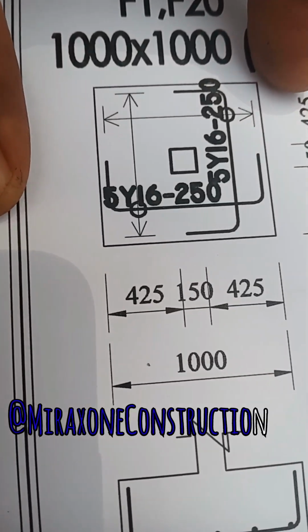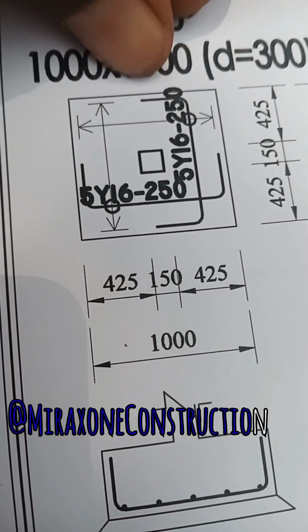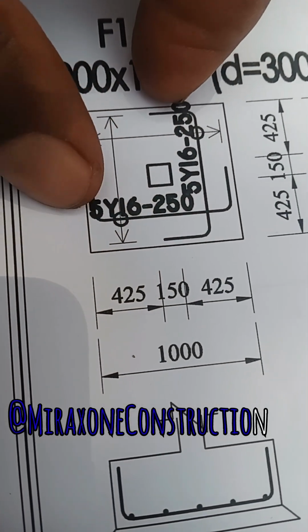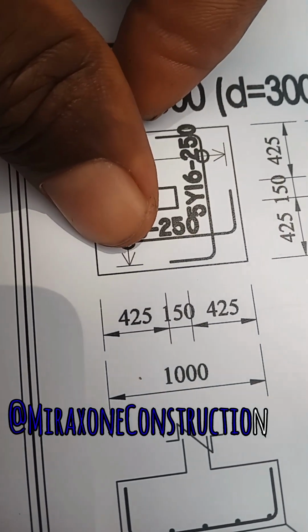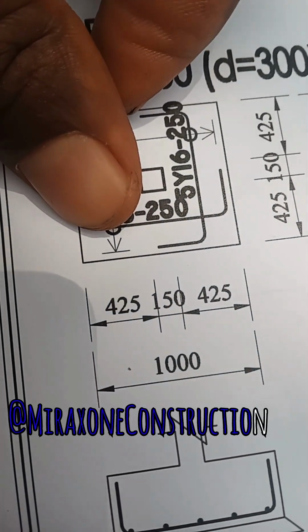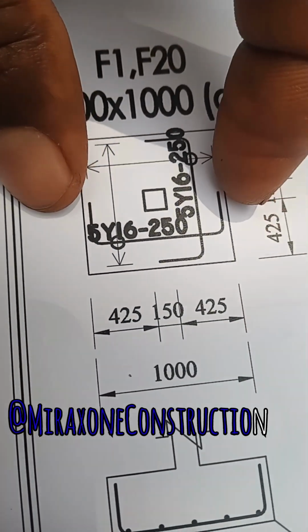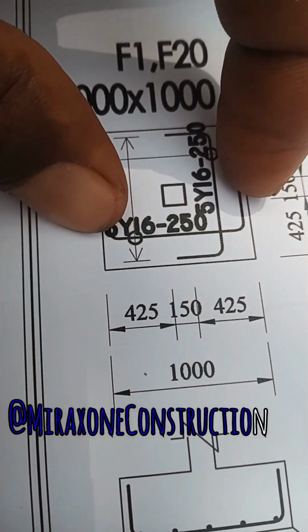Whenever you are cutting it, it's not going to exceed 1 meter because the length is 1 meter. You still have to give concrete cover, and it's going to have something like a hook. I think I have to show you how a footing looks after analyzing this drawing. So it's going to have a hook, and you have to cut it in 5 pieces.